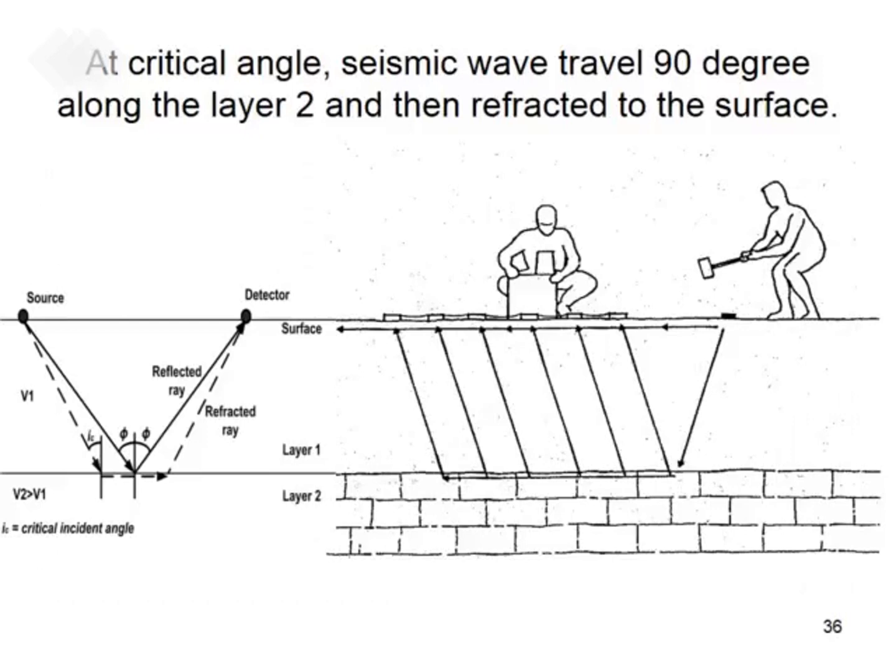Seismic refraction is measured by the travel time of the refracted wave. This refracted wave is created by giving an impact or shock at a point. For this example, this is the source point, and this impact or shock will create a wave that can travel along the layer. Different density of this material, layer, or rock will give different velocity and different wave speed.